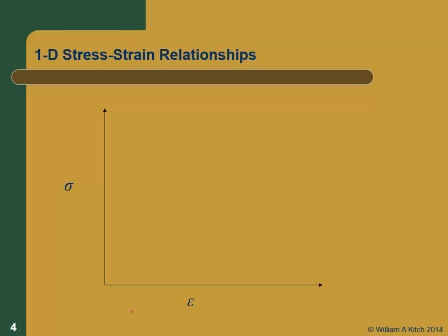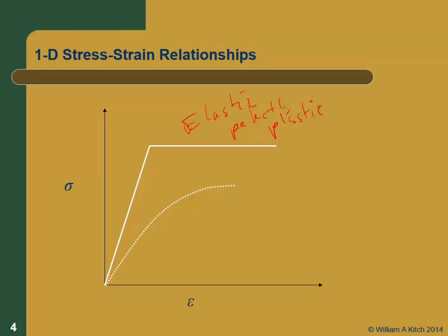Well, broadly speaking, there are 3 different stress strain curves you can have. This is an elastic, perfectly plastic curve, and we have an engineering material that behaves pretty close to that. One we can certainly model like that. What's the material that has a behavior that looks pretty much like that? It goes up, very elastic, and all of a sudden yields, and it's got this real long yield curve. Steel. A real steel stress strain curve would come out like this and go something like this, but you can model it definitely like that, and that's how we model steel. It's a very good model for steel.